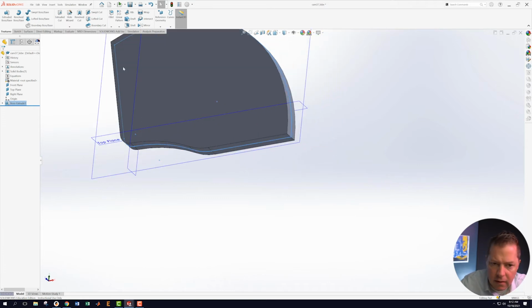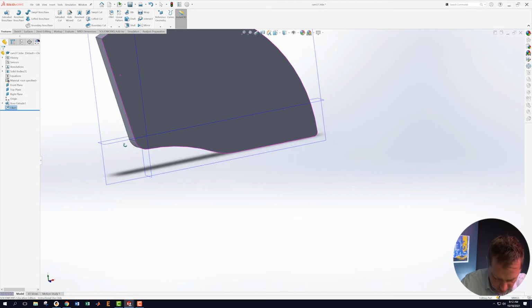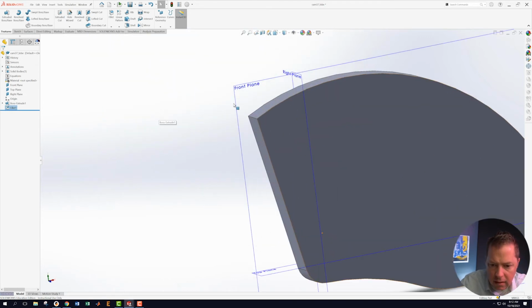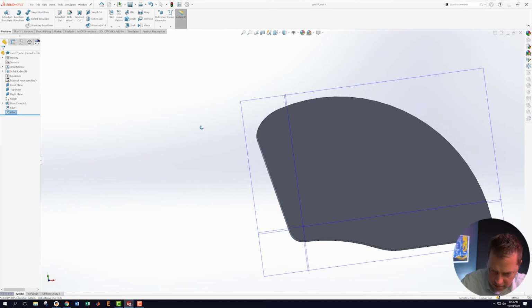So let's add in this fillet that's down here. Fillet 2. I want this to be 2. Yep. And this one up here says asymmetric fillet. Let's click on that edge and go over to fillet. Here's a symmetric one, here's an asymmetric one, and this says 15 and 10. So 15 and 10, and that actually is looking pretty close. Yeah, that's looking good.